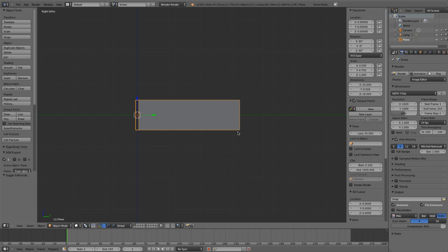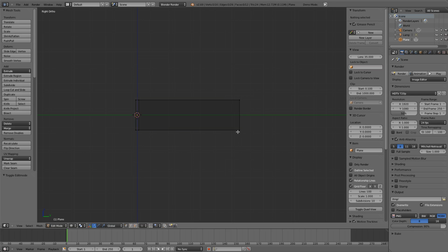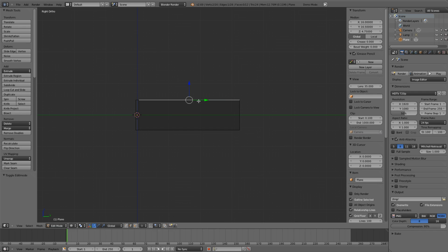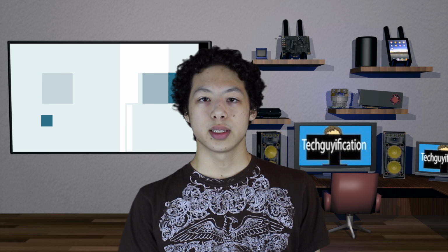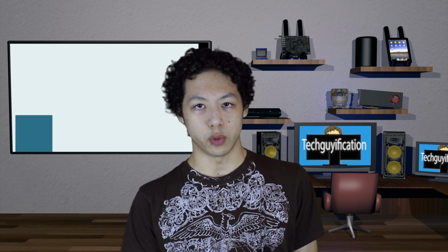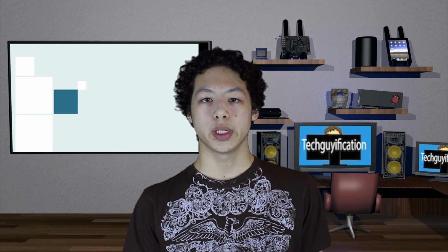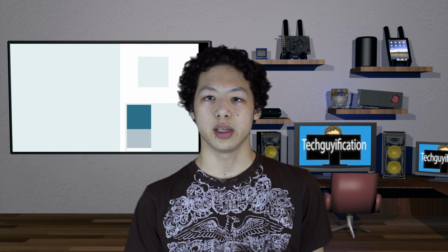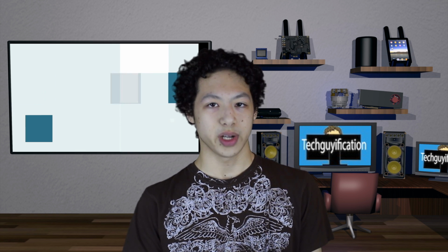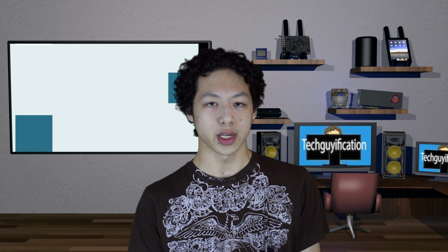So now go into right side view, which is numpad 3, then wireframe mode with Z, and tab into edit mode and switch the selection thing to edge select. Next, select one of the top edges of the wall. Now Control E to bring up the menu, and then edge ring, which will select all 4 sides for us.